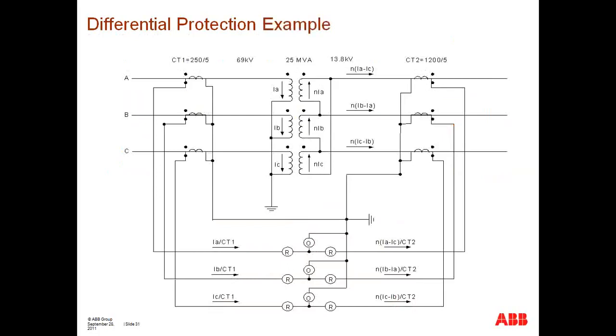In the past, with electromechanical or solid-state relays, we would use what was referred to as tap settings to provide the relay that information so that it would be able to perform this ampere turns balance calculation. In the case of modern microprocessor relays, most of the ones available from the major manufacturers just ask for voltage ratings and power ratings, and the transformer protection relay itself is able to determine what the ampere turns balance should be based on the currents injected into it.